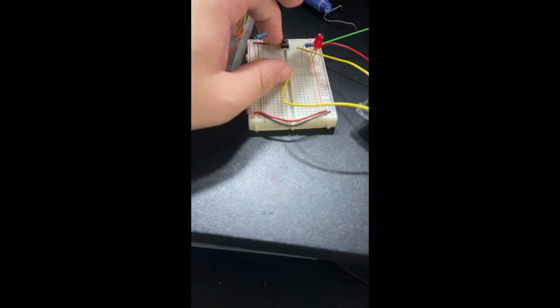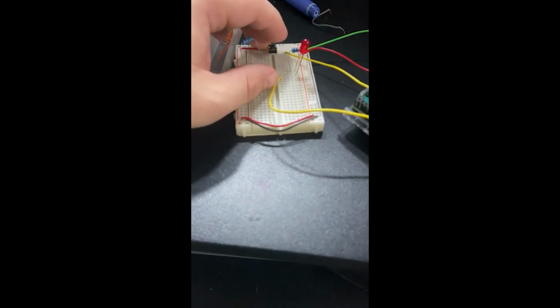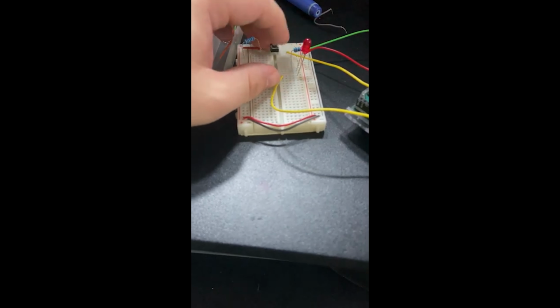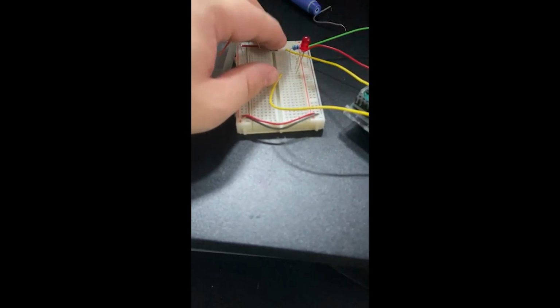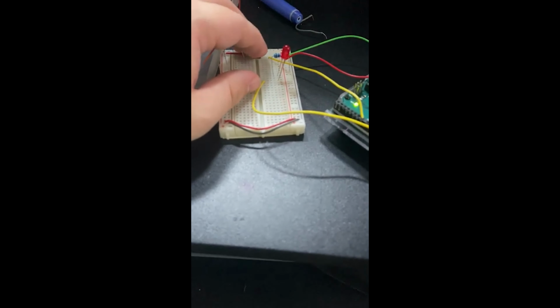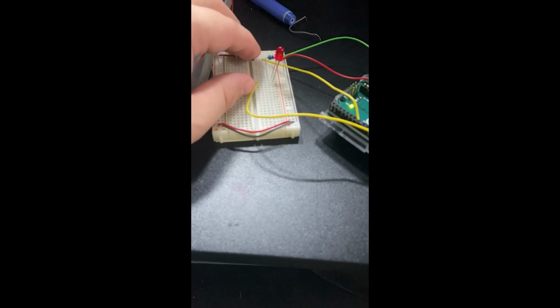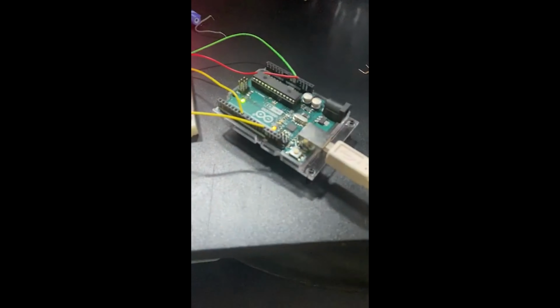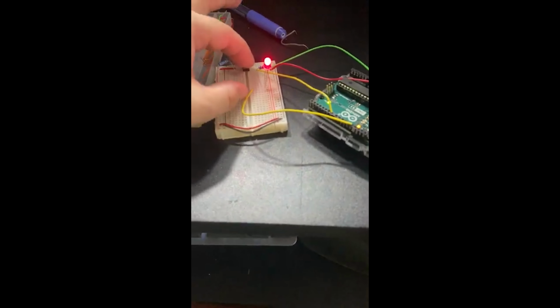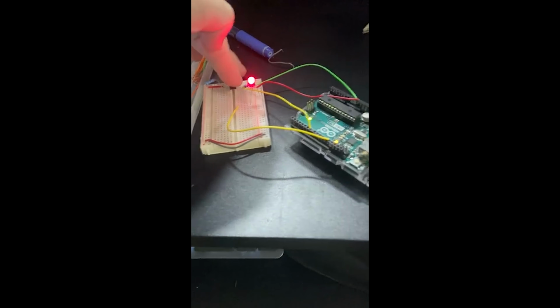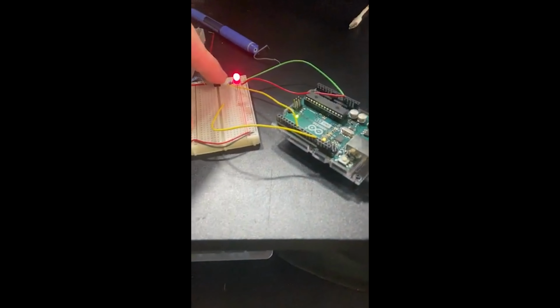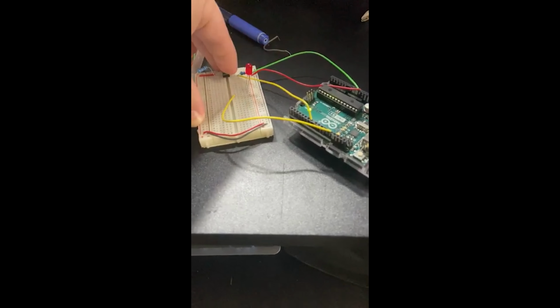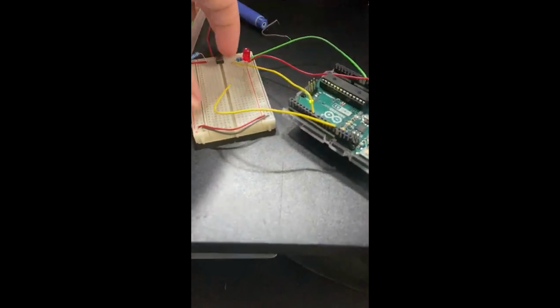I'll hold this in there with my middle finger, and as I press this, you can see that as long as the button isn't moving and making electricity move in weird places, it is now functioning as a power switch. There are other ways you can do this, but this is one where the Arduino is detecting whether or not electricity is flowing through the button, and then using that bit of logic to manually turn on and off this LED. So there's that. We can also see this in the code. Actually, not in this one.